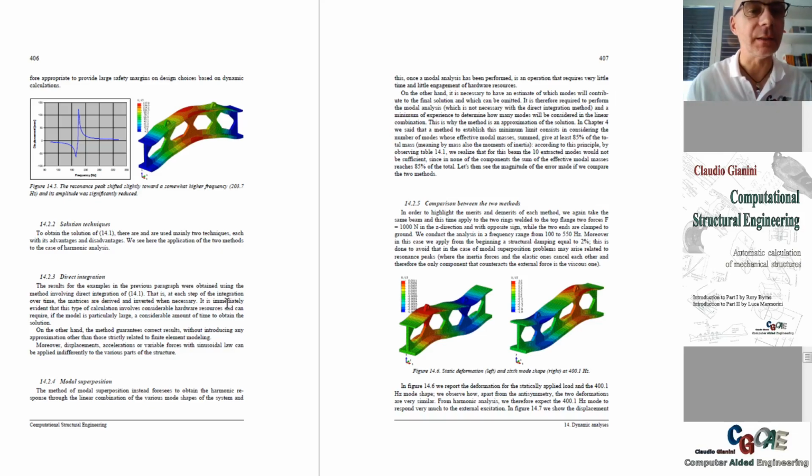Then solution techniques are discussed. So what kind of solution can be used? There are mainly two different ones. One is the direct integration, so the equation of motion is taken as it is and integrated directly, step by step. And the second one is the modal superposition.